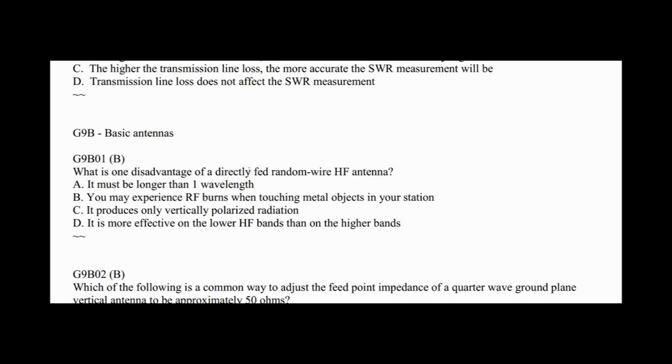What is one disadvantage of directly feeding random wire HF antennas? They say you may experience RF burns when touching metal objects in your station. Well, none of the answers make much sense, but that's very true.